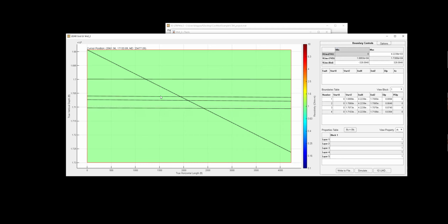They don't have to be exact right now. So we know that one fault, we can add a fault here, was at around 2,800, and the other one, we saw that it crossed a little bit past 2,000, so I'm going to give it some angle and have it pass the trajectory at a little bit past 2,000.